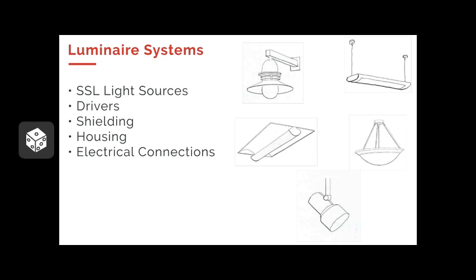Instead of ballasts, we need drivers. Drivers just look at the voltage and convert it from an AC voltage down to DC and a very low voltage. Also with solid state lighting, we can easily shield and do a whole bunch of different things, and dimmability that we couldn't do with the fluorescent or the metal halides or high pressure sodiums.